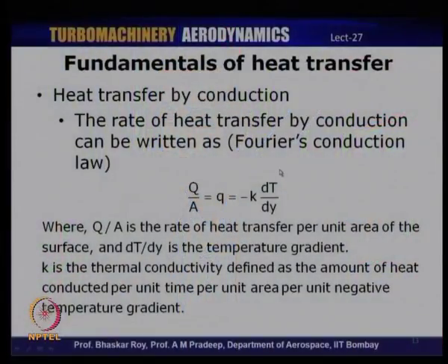Now, let us take a first look at conduction in a little more detail, and subsequently we will look at convection, and both of these of course, in the context of heat transfer in a turbine blade. One of the fundamental laws of conduction is the Fourier conduction law, as I am sure you must have learned, which basically relates the rate of heat transfer to the temperature gradient, and that is through the thermal conductivity.